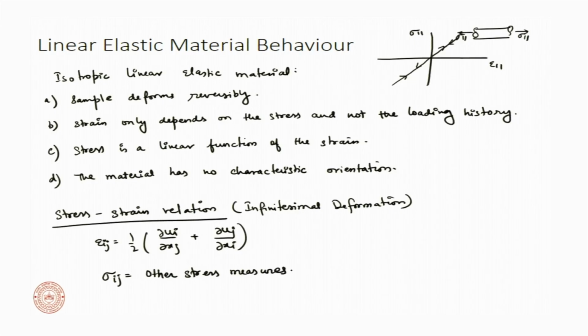All right. So, the first formula that does come to our mind is that sigma is equal to E epsilon. This was our Hooke's law, and that is something that we have studied very thoroughly in our undergraduate, right? And so, the uniaxial stress causing strain is proportional to this elastic modulus. Okay. Now, since we are doing this more from a modeling perspective at a postgraduate level, we should be able to generalize this expression and look at all directions possible.